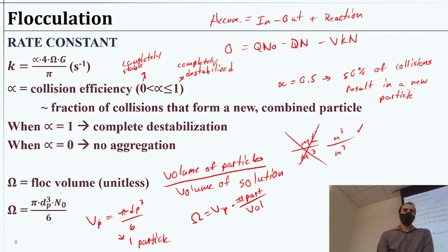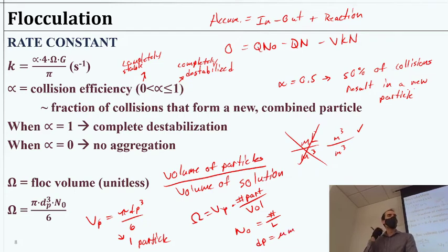And the thing here is n naught, we're often going to have to convert the units. Probably diameter of the particle as well. So n naught is often maybe number per liter, and then diameter of the particle might be like micrometers. So we certainly have some unit conversions to do to make sure that instead of liters, we get cubic meters.